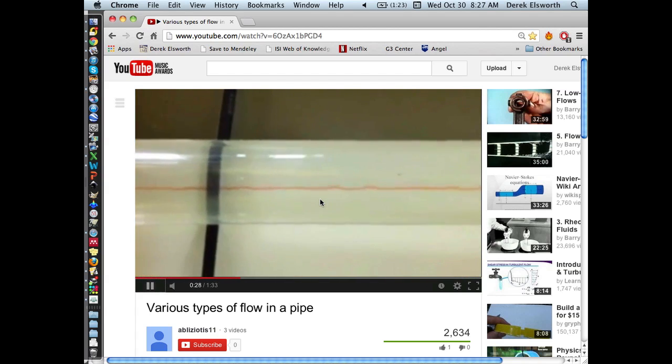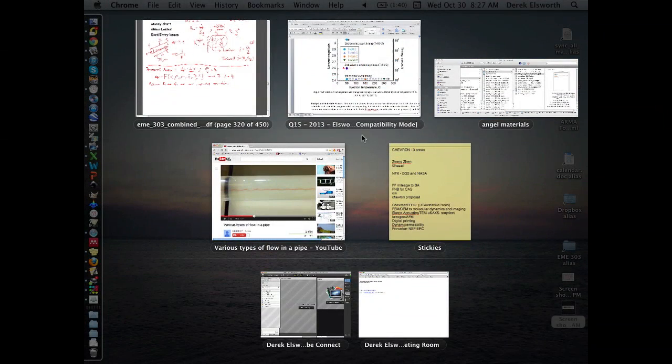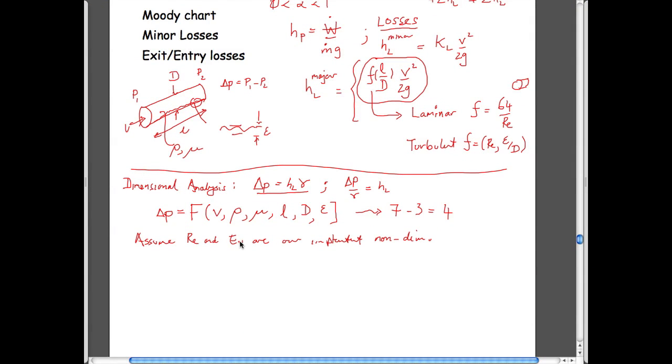So why Euler number? Well, the reason is that we also know that the forces on structures, in other words, the change in pressure from going upstream to downstream, is indexed with the Euler number. And so we used it for the calculations with wings. We used it for the calculation with flow impacting on a satellite dish. It's really not very different to have flow occurring in here. It's just that in here, the flow going along has some shear stresses acting against it, and it's that which dissipates the loading that goes through there.